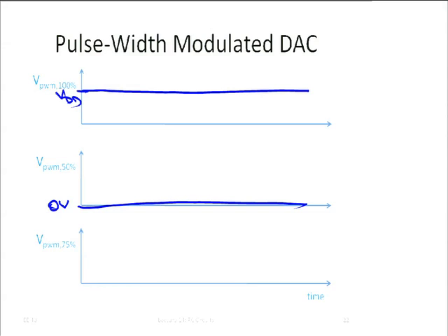Well, what about the following thing? The microcontroller really runs off a clock, right? We maybe have generated with the timer that we just discussed. So if under program control, we tell this thing to leave the output high during 3 clock cycles, then get it low during, okay, during 3 clock cycles, we leave it high, right?